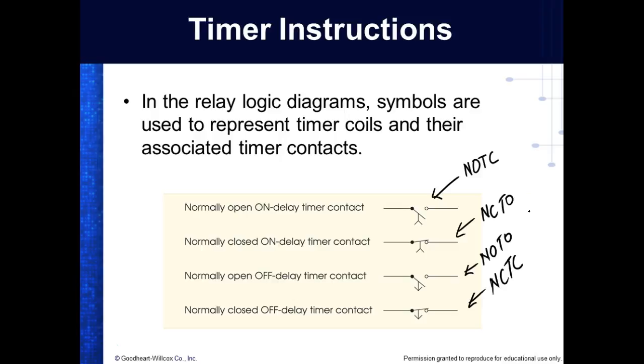What you've got to do is picture, this is an on delay timer, right? You understand? So it's normally open. We put power on the timer. What's it going to do? After a time, it closes. So normally open timed closed. Notice on your on delay timers, it's backwards. Normally open timed closed, right? Normally closed, what? Timed open. On your off delay, they're the same. When I energize an off delay timer, this contact closes instantly. When we take power off the coil, it's timed what? Open. And this is a normally closed timed close.